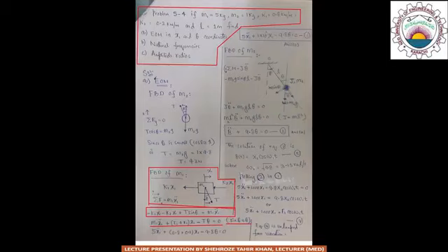or by substituting the values of m1, k1, k2 and T in the above equation, we get 5 x1 double dot plus (0.8 plus 0.2) x1 minus 9.8 theta is equal to 0. Since we are required to find out the equations of motion for the system in terms of x1 and theta coordinates,